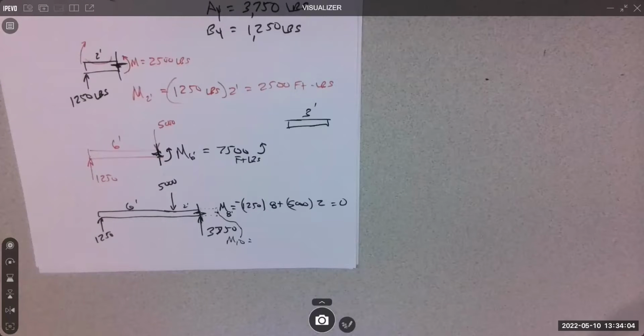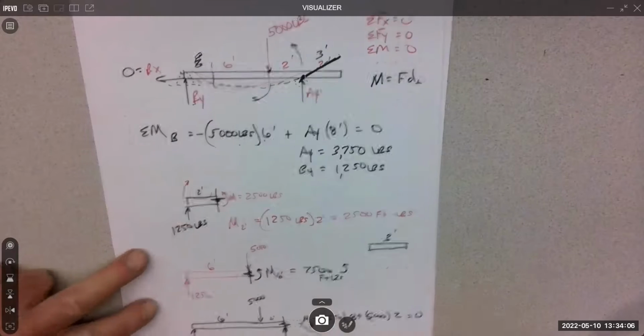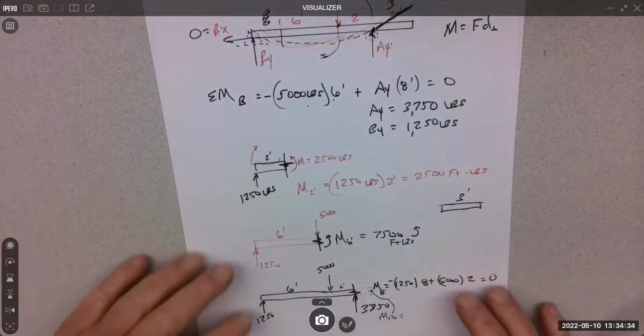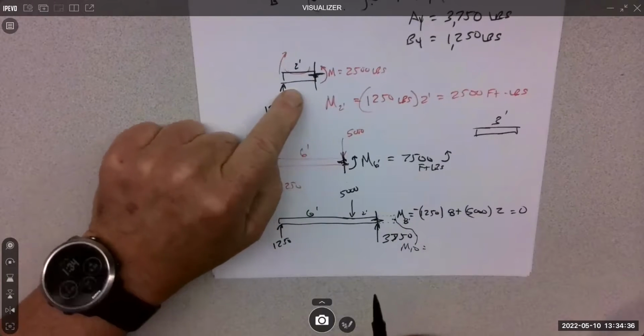All right, very good. So the other thing, that's the moment. The other thing we want to think about is what's called the shear force. So the moment is the internal rotation of the beam. The shear force is literally a force, vertical up and down, that also occurs, that is trying to literally shear the beam off. So that happens in beams, and we need to think about that. It's not usually the control. It's usually a secondary thought, but this is how you get it, by sectioning the beam.